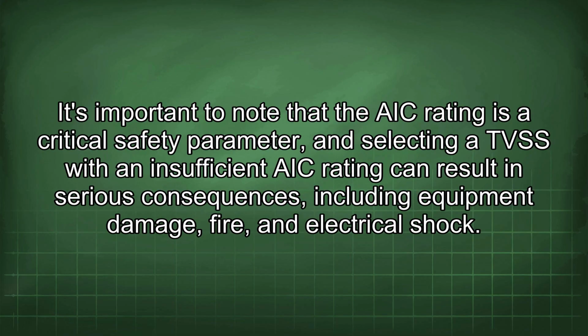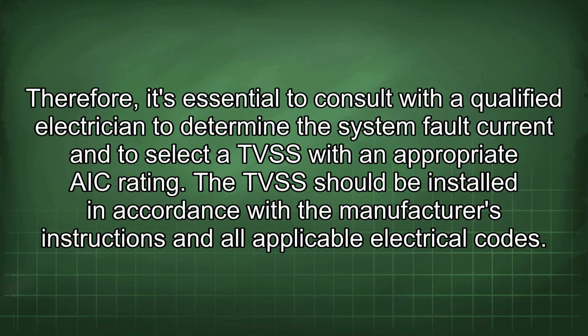It's important to note that the AIC rating is a critical safety parameter, and selecting a TVSS with an insufficient AIC rating can result in serious consequences, including equipment damage, fire, and electrical shock. Therefore, it's essential to consult with a qualified electrician to determine the system fault current and to select a TVSS with an appropriate AIC rating.